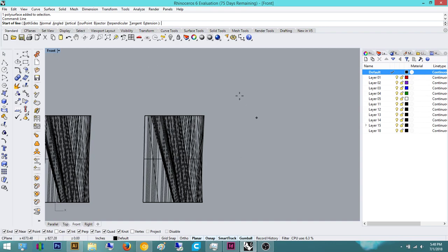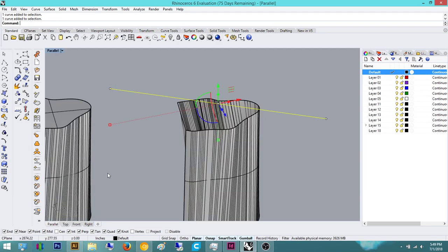So now, here is another lesson combining curves and the surface. We can start to manipulate this geometry by just drawing a curve in profile view. This is a front profile view, and just like that. Just make sure this line geometry, or curve, extends past the bounding edges of this object, because you're going to be using this later to quote-unquote slice it. So I just drew it way over, because it doesn't matter. I did that, and now you're left with this.